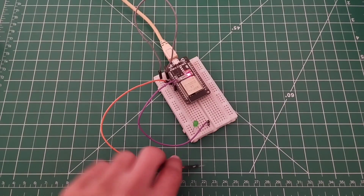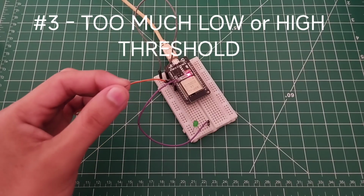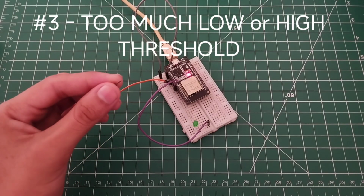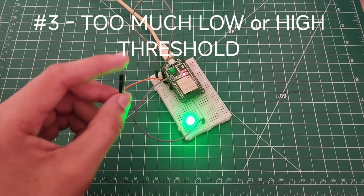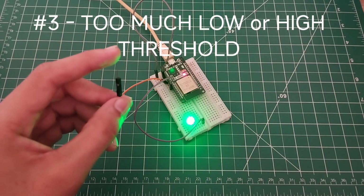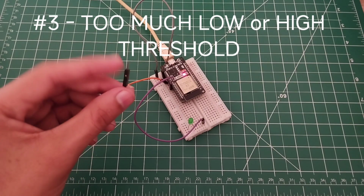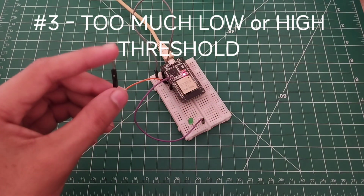And the third mistake is that if your threshold value is too low, then no matter how hard you touch this wire, your LED won't turn on or off. And if the threshold value is too high, then even a gentle or accidental touch would be detected by this ESP32, and your LED would turn on or off, right? So you need to select the value according to your requirements, based on how sensitive you want your project to be.